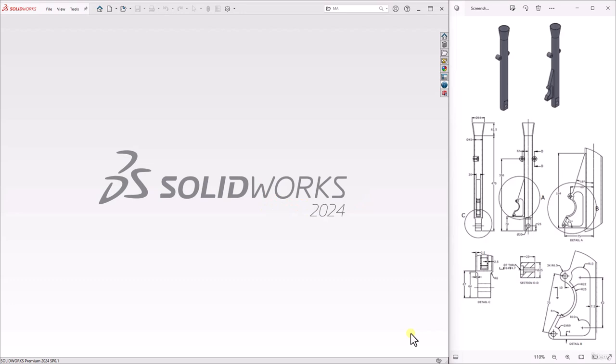Hello everyone. In this tutorial, we will create two essential components of a motorcycle, the right fork outer body and the left fork outer body, and the detailed sketch is shown on the right. First, we will create the right fork outer body using the different feature creation tools of SolidWorks as the first configuration, and then you will create the left fork outer body as the second configuration by suppressing some of the features from the right fork outer body.